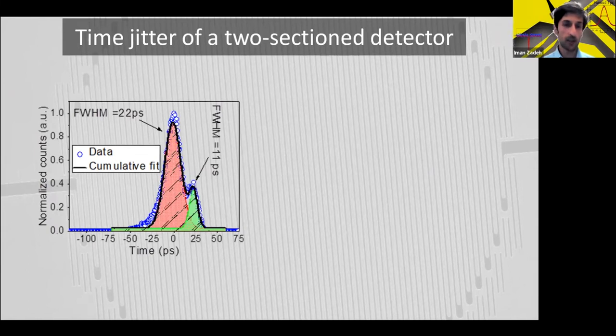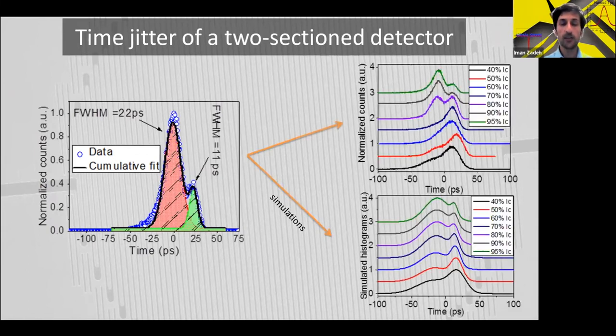And we then swept the bias current, and you can see these 2 peaks move. Initially the one on the right is a bit more prominent, and as we increase the bias current, the wider nanowire shows more significant detection. Because it has larger surface area, at the end that will prevail. This is in good, or at least decent, agreement with our simulations.